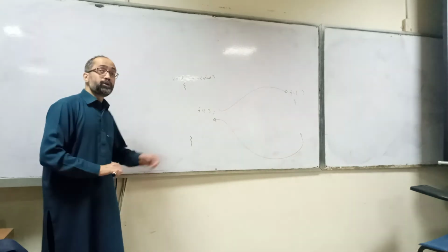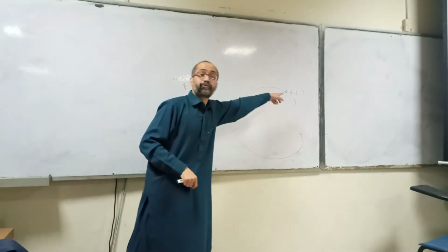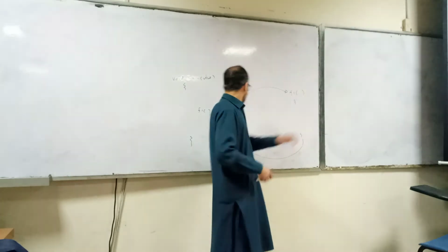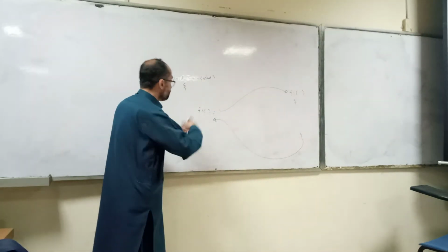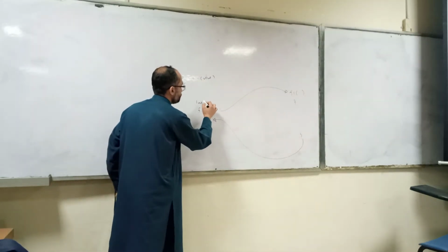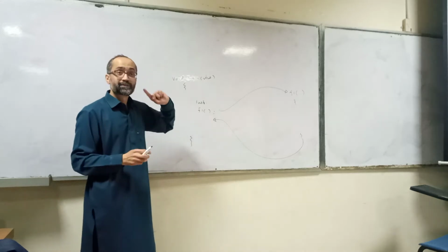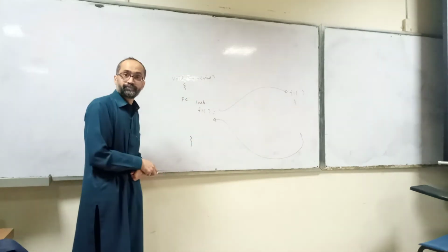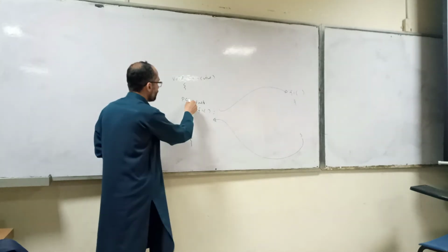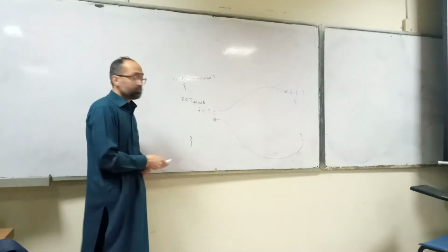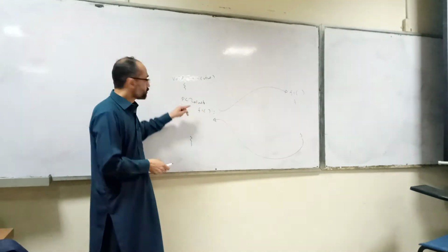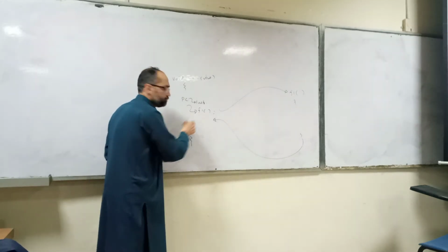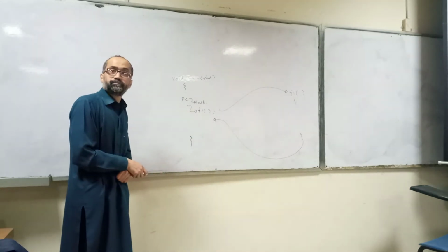So actually, when you are calling a function, the control is transferred to this f1. Now if you look at this, maybe there is some instruction here, the last instruction before this call. The program counter was pointing to this instruction. But when you are calling a function, the program counter will be updated, now pointing to this function.